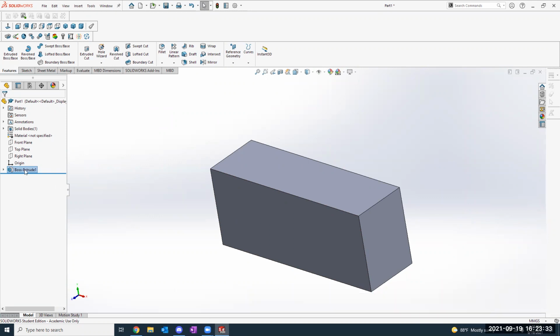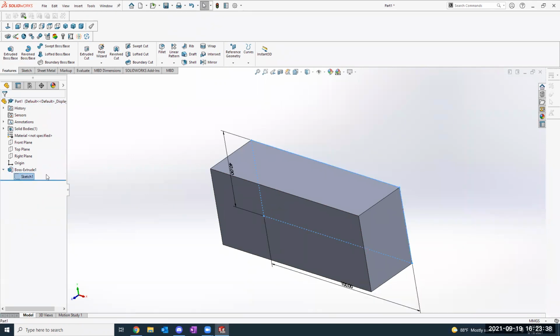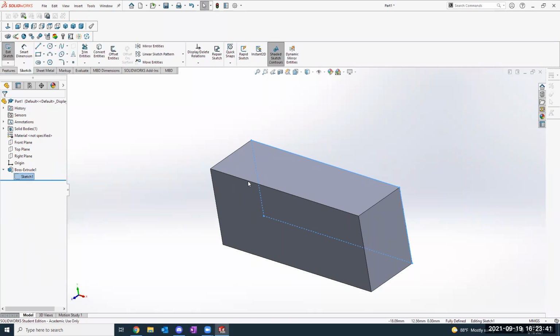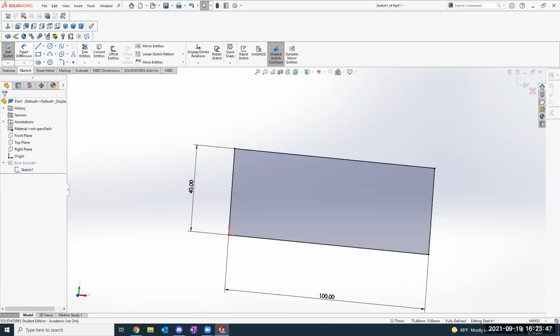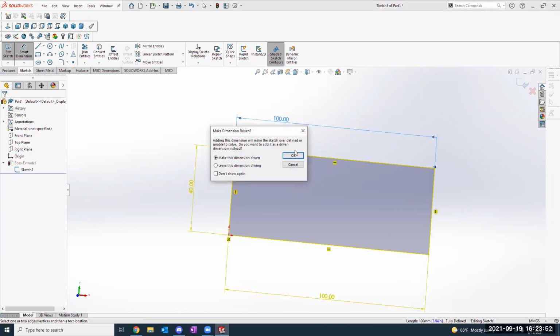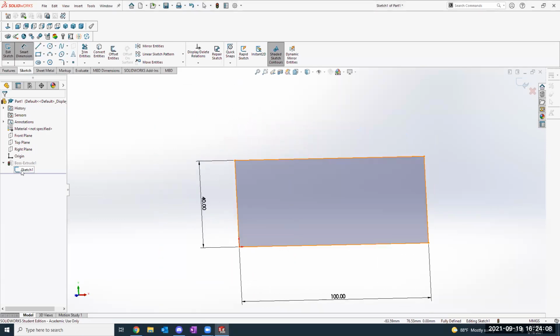And could you show the tool for length again? I think we go ahead and go into our sketch here. And then our tool for setting the length was Smart Dimension, where you just click on your line, place the dimension, and then normally you'd be able to type it in and change the numbers from there. But since we've already got that side constrained to 100 millimeters, it's not going to let me do that. So I'll just go ahead and cancel that and then quit editing.